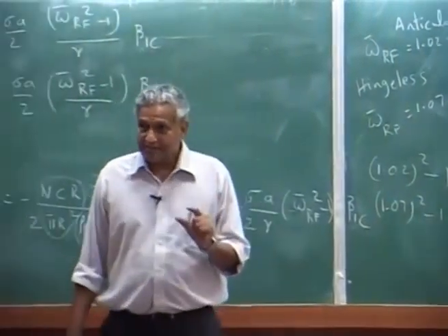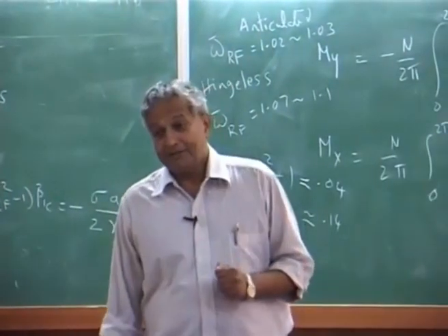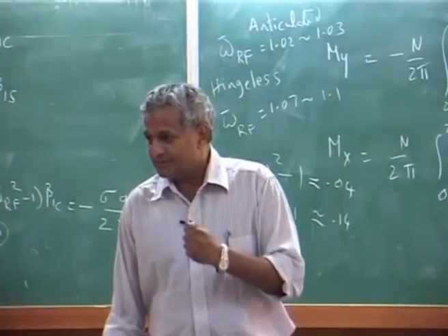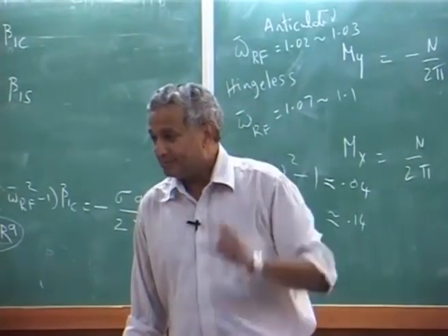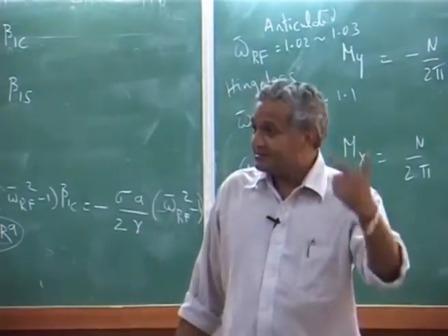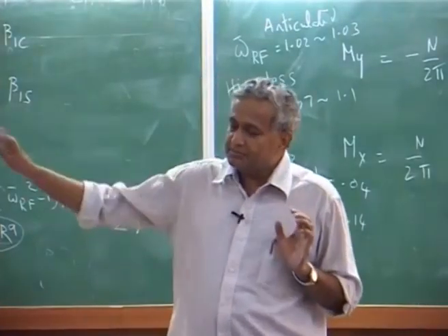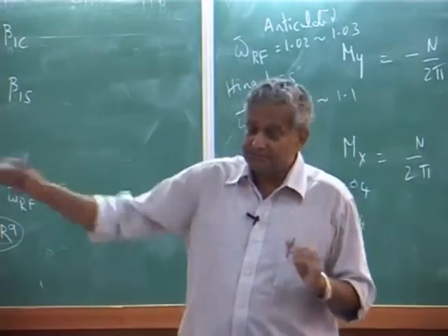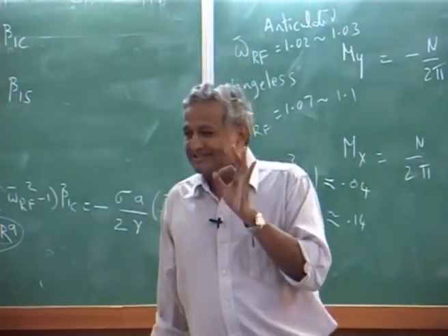Because you find flap frequency is a very, very dominant parameter, really influencing. So, industry spends enormous time in deciding and in going through the iterative thing, several designs. Now, imagine you are actually making a composite blade with a hub design, you must know the flap frequency to the third decimal.